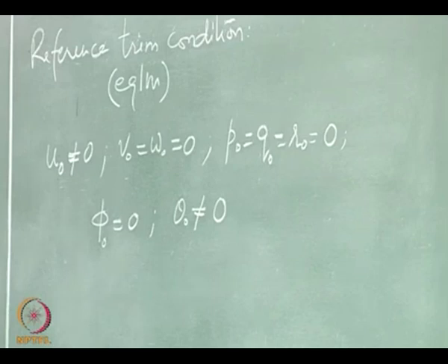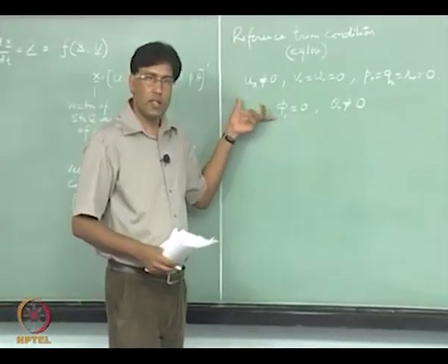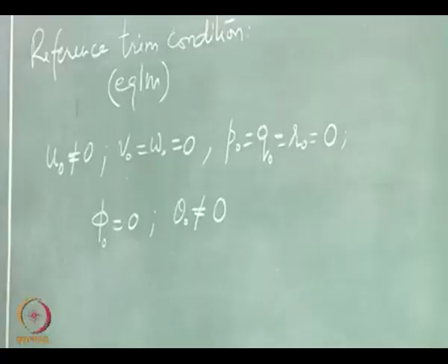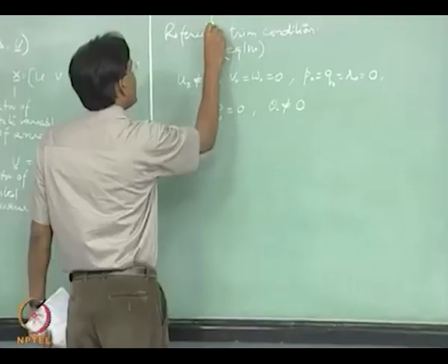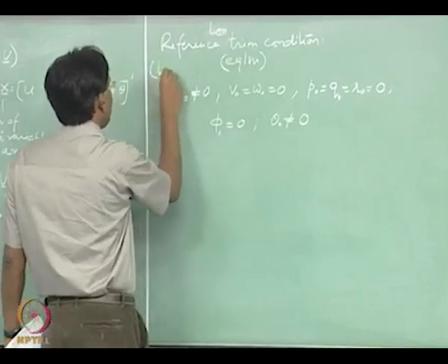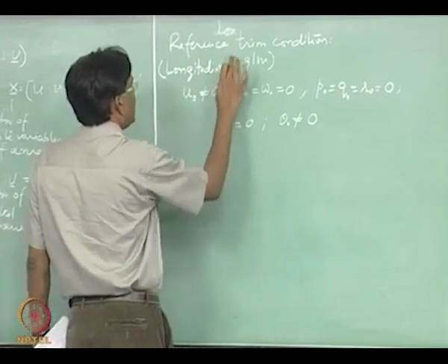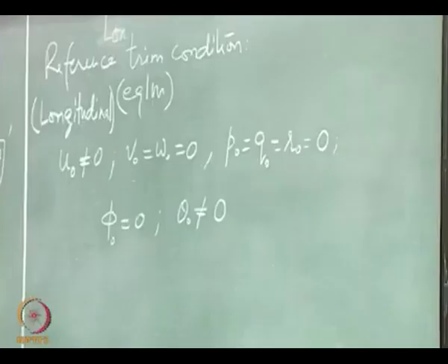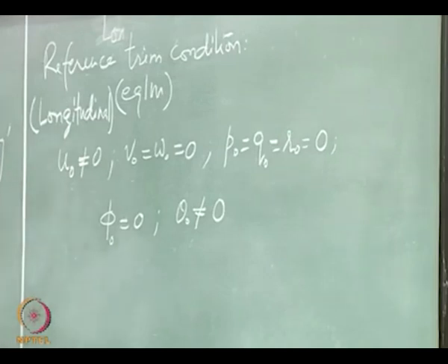Now, we want to linearize our equations of motion around this longitudinal equilibrium condition. And I said that we can introduce perturbation from this equilibrium condition.